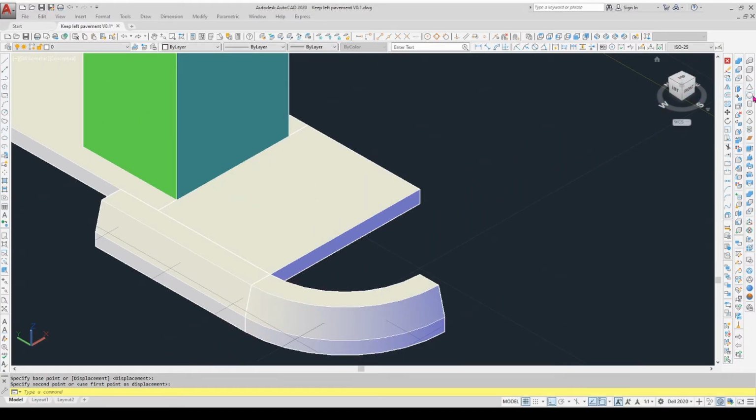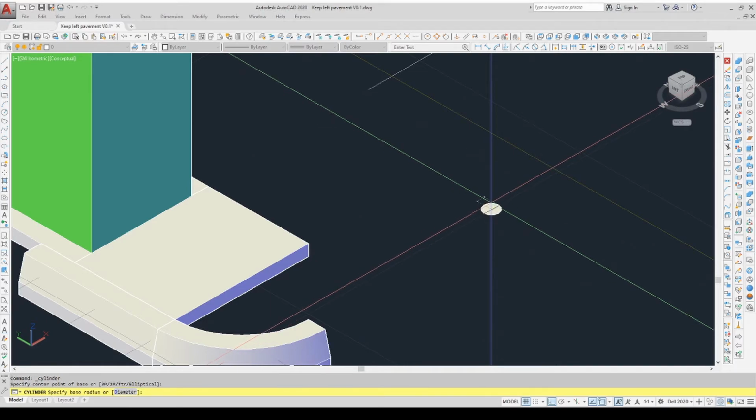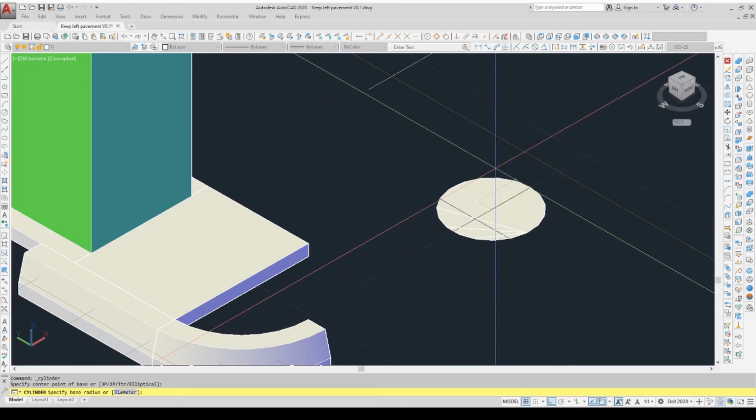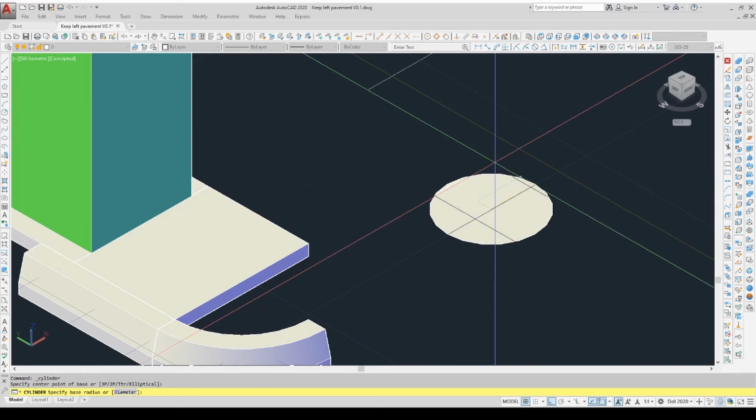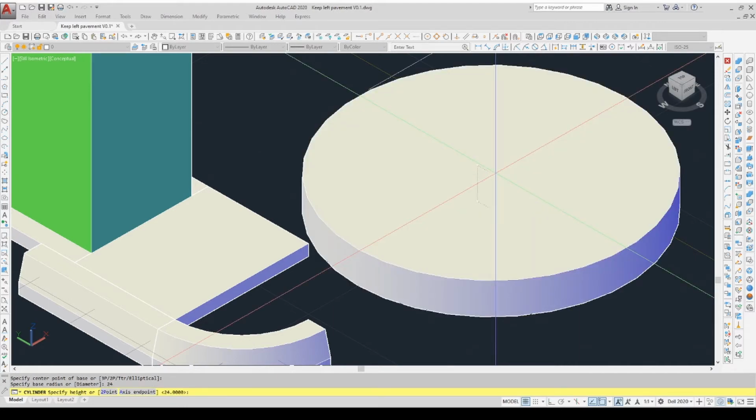So we have a command which is a cylinder. We just move over here and we pick a point in the center of the cylinder, and we now need to define the diameter. So it's actually in radius or diameter. You can choose which one you want. So the diameter is going to be 24, and it's gone for the...